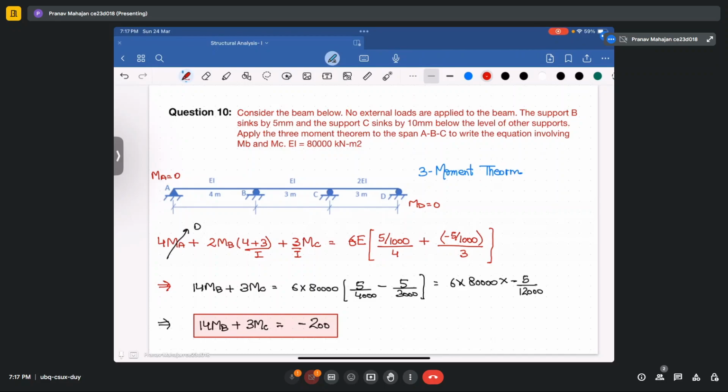So in here what we have done, we have first removed the indeterminacy or redundant force that is there in the member. Then we have applied the unit load at the point where the redundant force is considered, and then with the help of the consistent equation we have determined the value of the unknown or redundant reaction at that particular point.